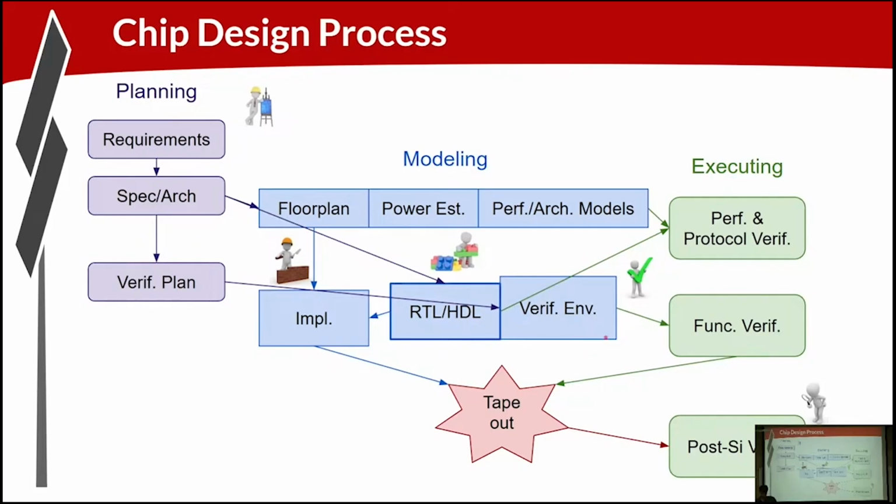All of this is the modeling that's done. You're also working with those models. So the performance and architectural models allow you to do performance modeling and verification work. The verification environment and the RTL enable you to do functional verification work. So writing test cases, running those test cases, and debugging those failures, etc.